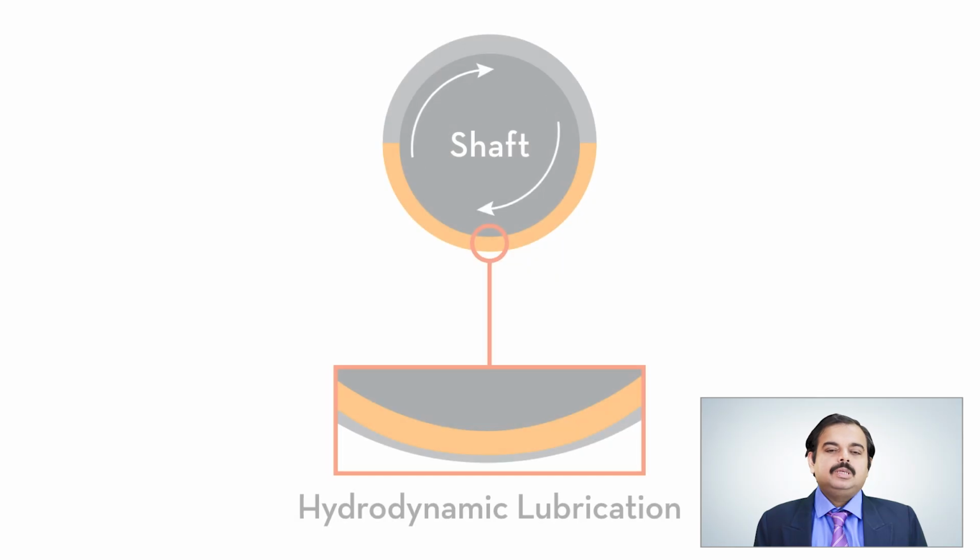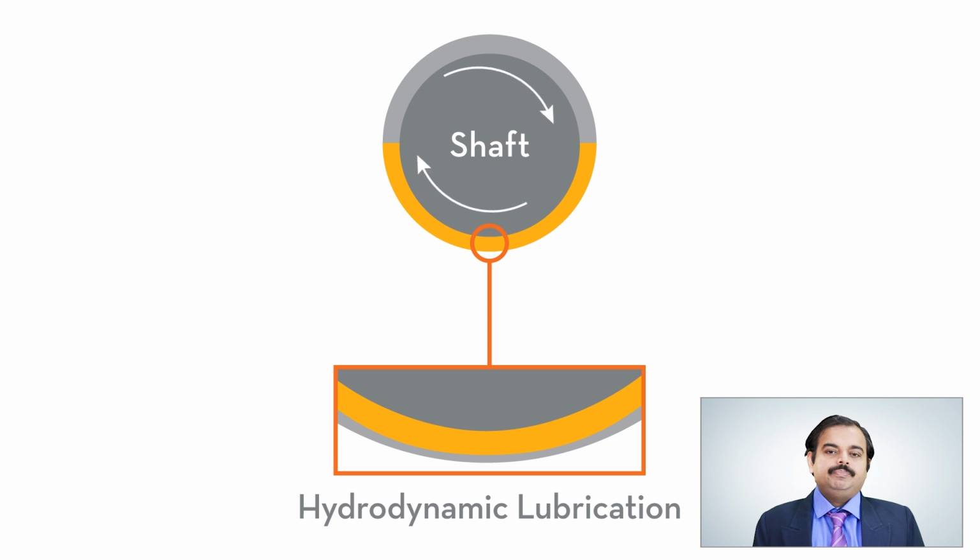Jacking oil pump supplies high pressure oil to jack up the turbine generator shaft to prevent boundary lubrication, and may also supply high pressure oil to drive the hydraulic motor for the turning gear, also known as the barring gear. During startup and shutdown, auxiliary oil pump supplies the control oil. Once the turbine speed is more than 2850 rpm, the main oil pump takes over.